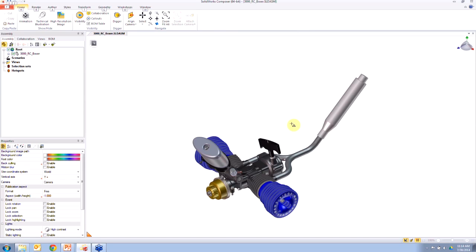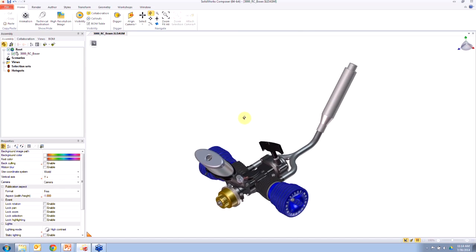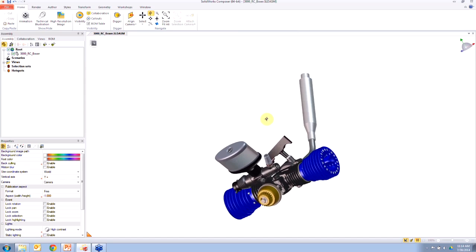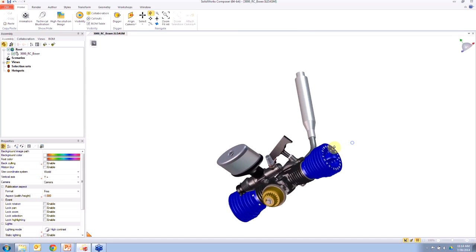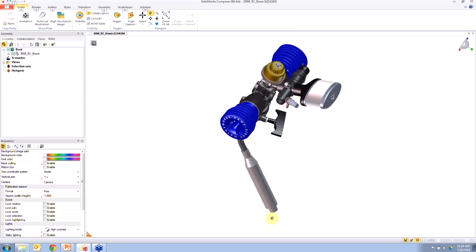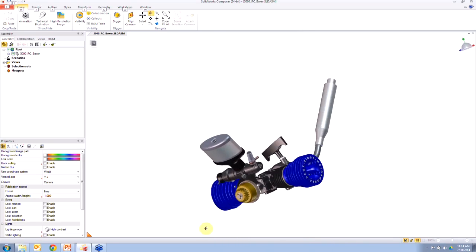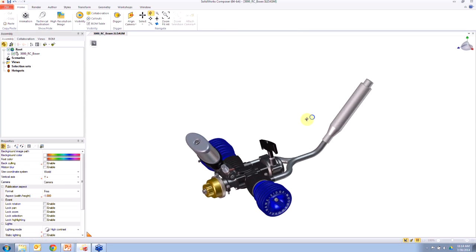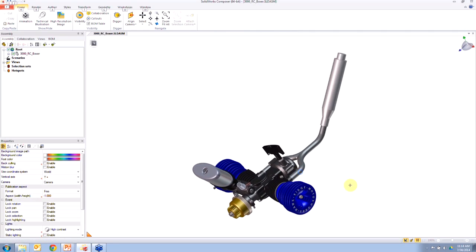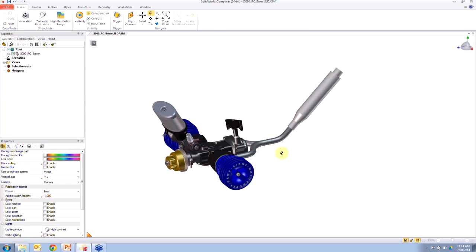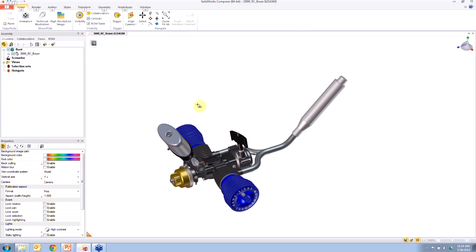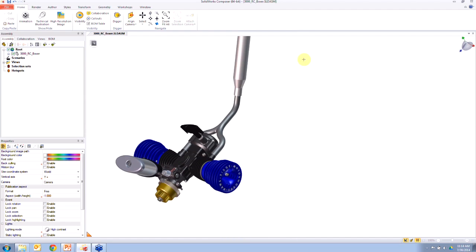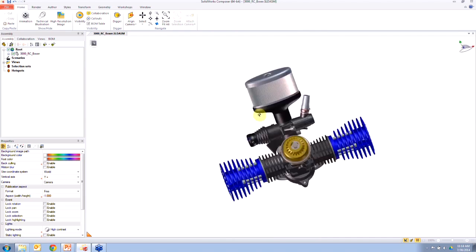Now Alt, if you hold down Alt and you right click rotate, it rotates around an axis. So if you want to rotate around a specific axis, hold down Alt and you can get that to spin in 3D space. Like right here, I can spin it along. It looks like it would be relative to the view of the Z-axis, even though it's not the Z-axis on the model. That's really good if you're holding Control, rotating something like this, and you just want it to rotate a little bit counterclockwise to reposition on the screen to get it to fit. Okay, so that's the rotate.